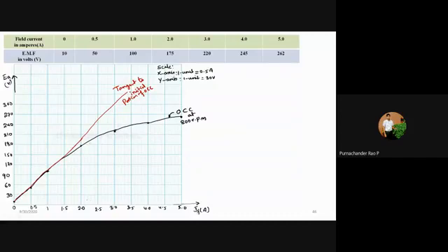So we'll take 2 points to find the critical field resistance, because the slope of this tangent will give you your critical field resistance. Am I right? Write that: the slope of the tangent to the open circuit characteristics will give the critical field resistance RCR. The slope of the curve will give us the critical field resistance.